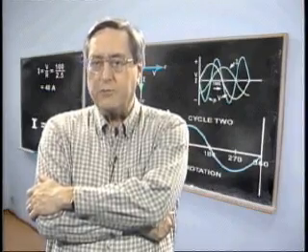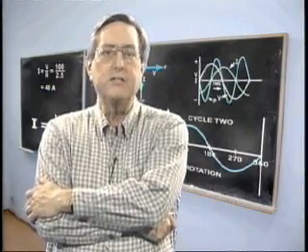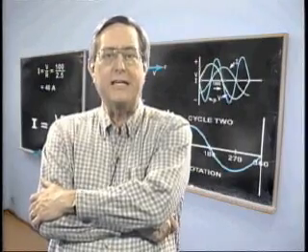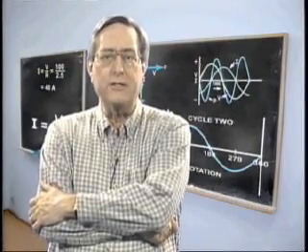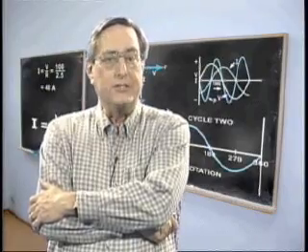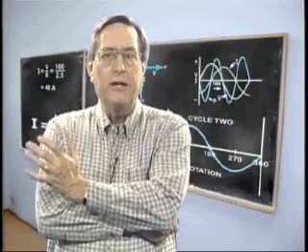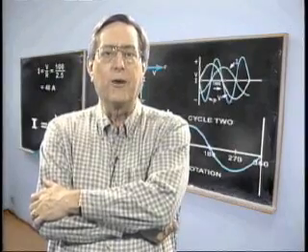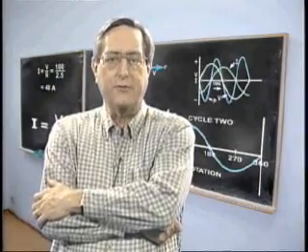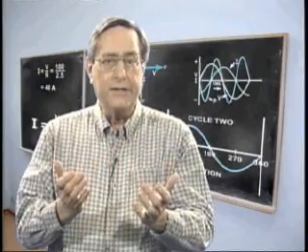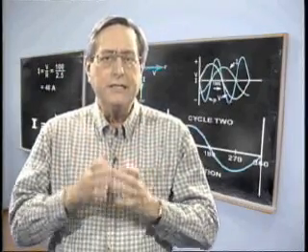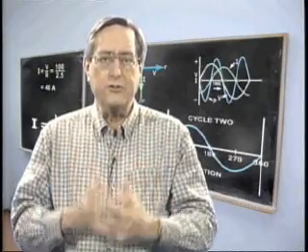The distinction between power and energy is very important. Please keep in mind that power is an indication of the rate at which energy is being consumed. This data is useful, for example, when calculating the size of cable that would be required to supply a particular amount of electricity. On the other hand, it would not help you calculate the amount of fuel that you need to have on hand to produce this amount of power.